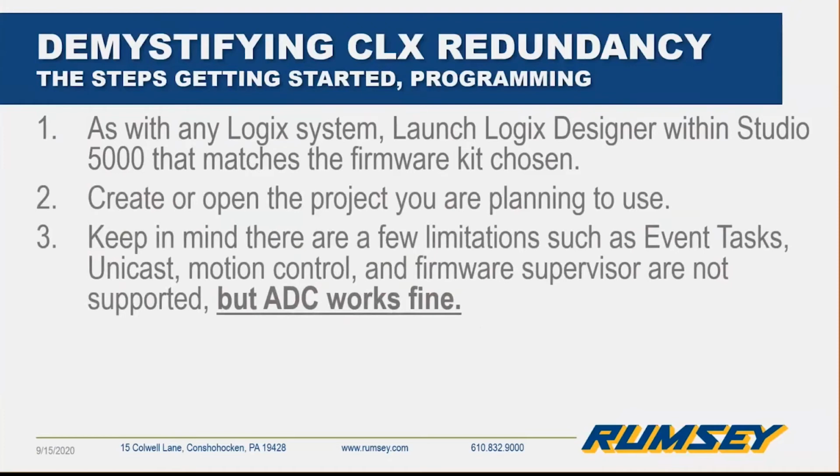Now, ADC does work. If you've seen some of my videos on the ADC, it will replace all the parameters, just not the firmware itself. For instance, my example is a 525 drive. You can still add devices hot. So if you're in run mode in ControlLogix redundancy and you want to add a 525 drive, you can do that hot. It's just like online edits, that still works. But again, the firmware will not be supported in the redundant setup.